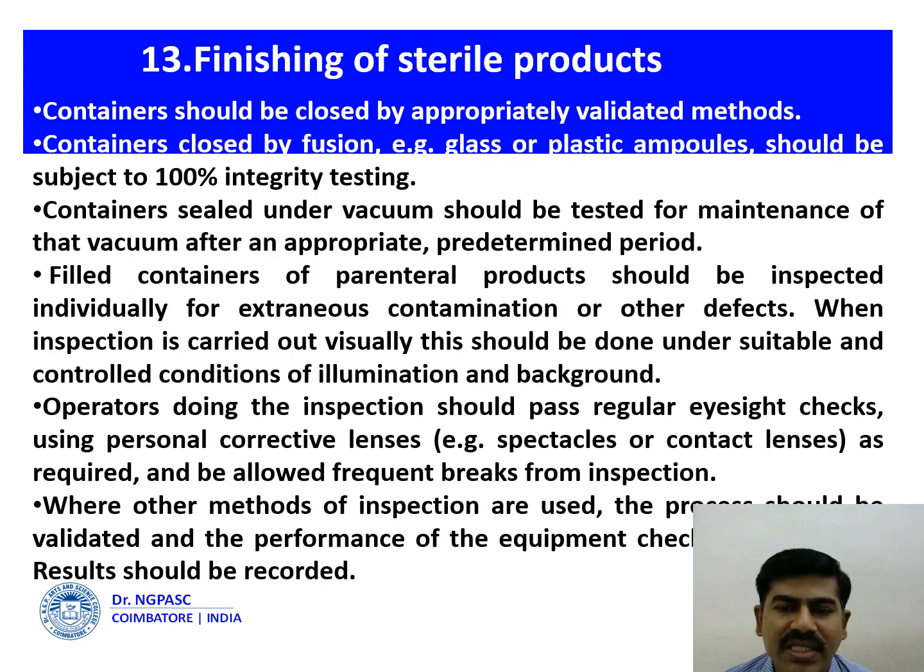Finishing of sterile products. The container should be closed by appropriately validated methods. The filled containers of parenteral products should be inspected individually for extraneous contamination or other defects. Operators during these inspections should pass regular eyesight checks using personal corrective lenses. Where other methods of inspection are used, the process should be validated and the performance of the equipment checked.